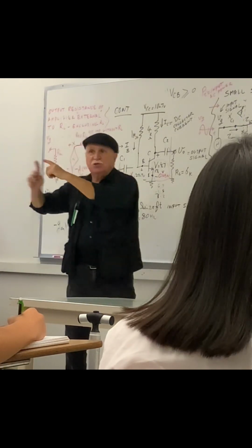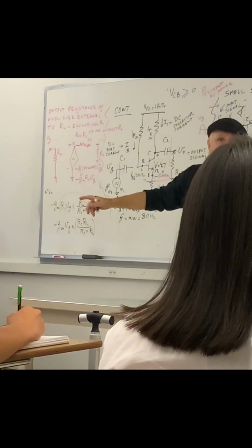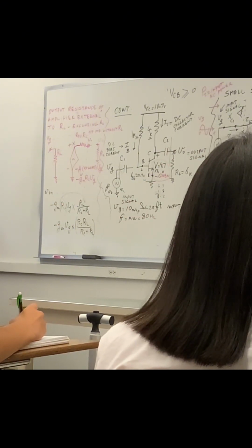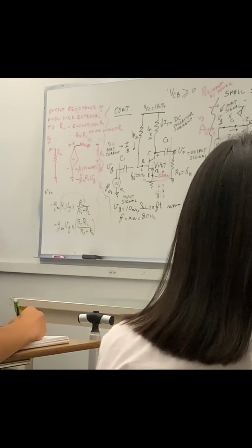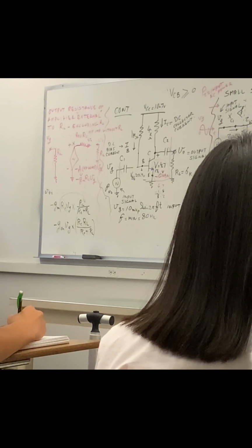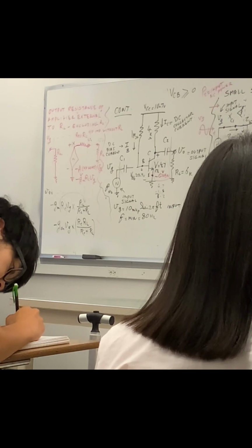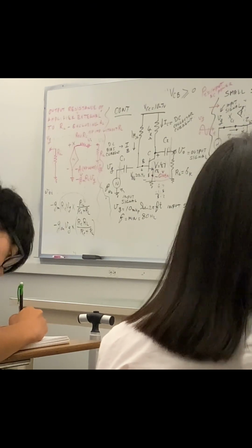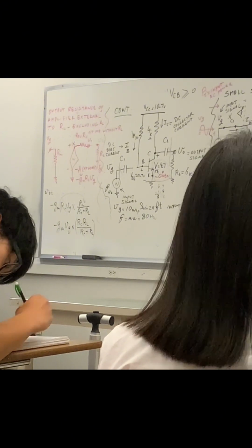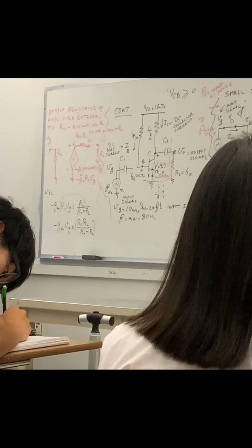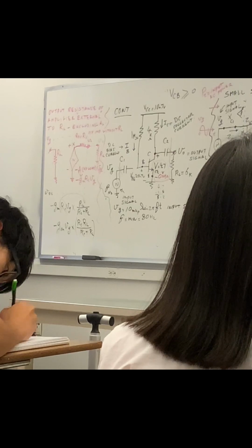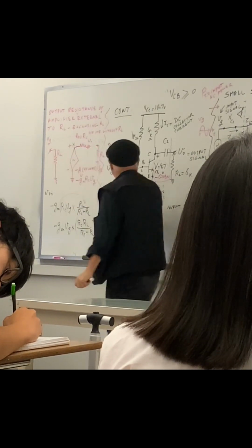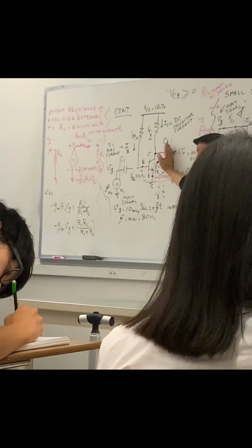And I can calculate the overall gain from input all the way to final output if I have 2, 3 cascaded stages. So that is why we are trying to isolate one stage into an input impedance, a voltage source, and output resistance. What comes next as a result of coupling can be computed very, very easily once you create these two parallel line models.